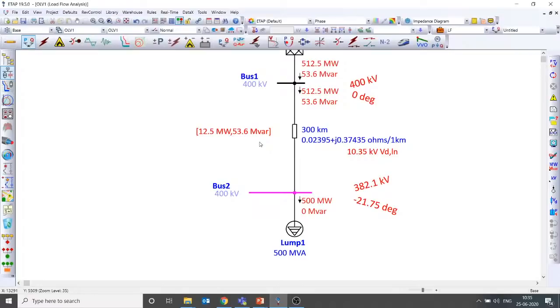Or I will put it the other way around: there are many simple methods better than Newton Raphson to find out voltage profiles, losses, equipment loadings, etc. in low voltage systems, which are radial in nature.